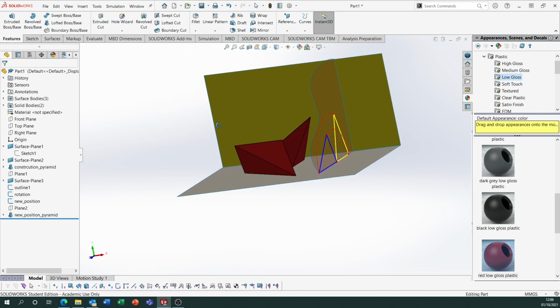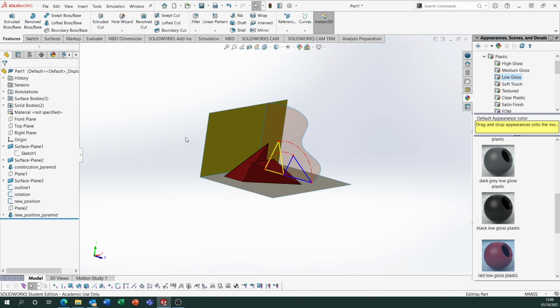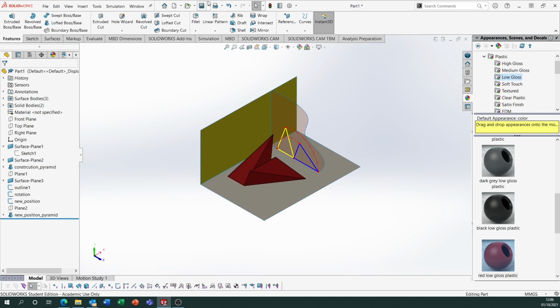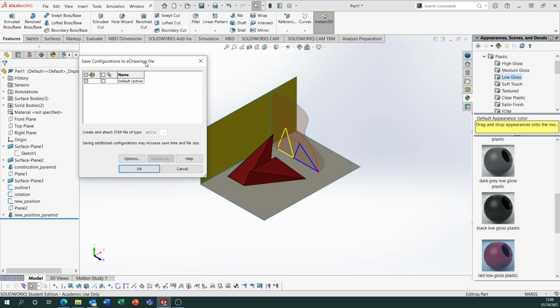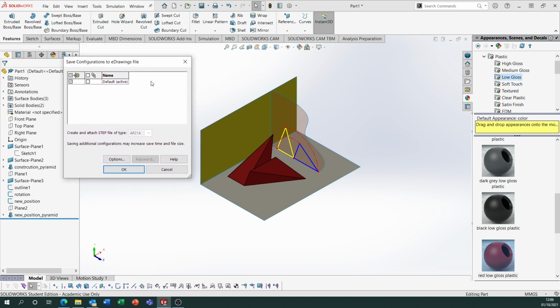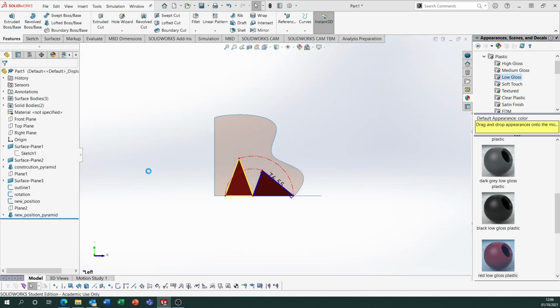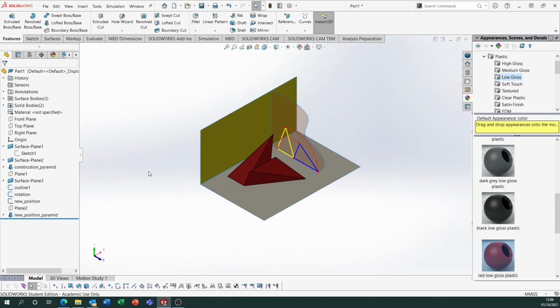Okay, something else I want to point out this week, and I want you to try out, is to export this to eDrawings. So if you go up to the Save button, click the drop down arrow and say Publish to eDrawings. Now don't do that until you've put in all the labels as well. So this pop-up will come up then, just click OK. It'll do a few movements to get the different views, and it might take a moment then for eDrawings to pop open as well.